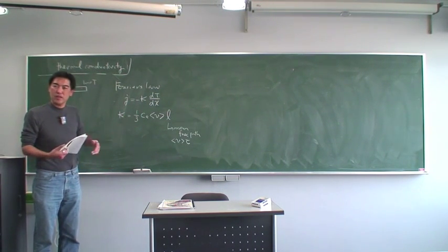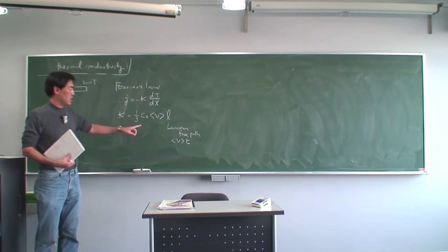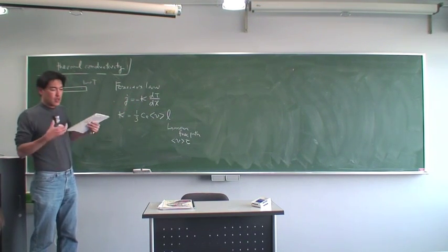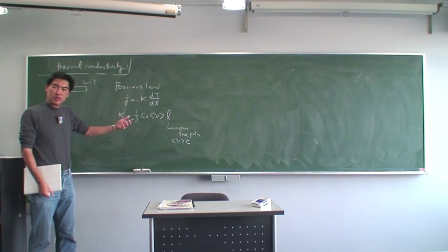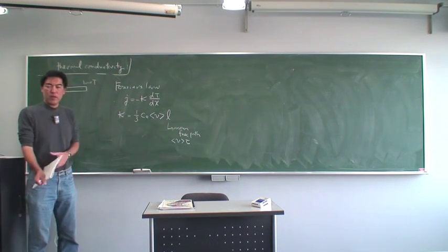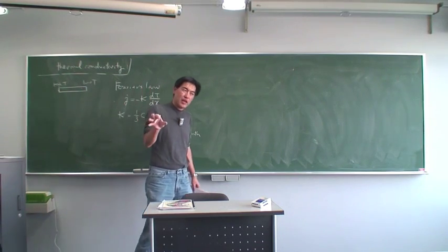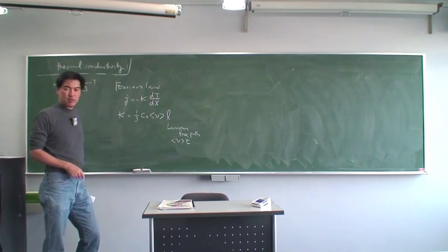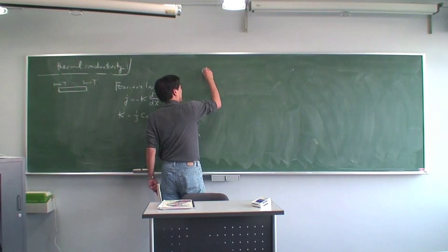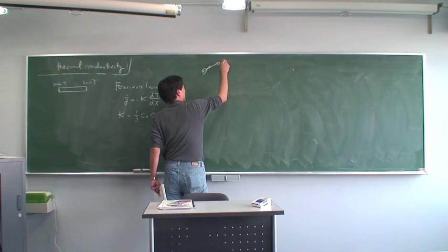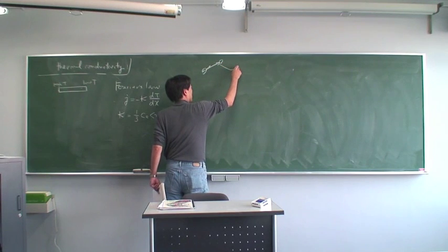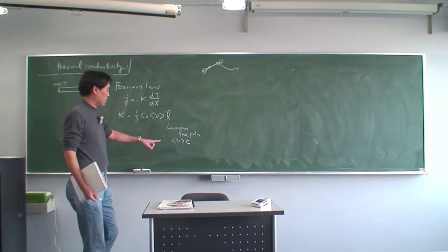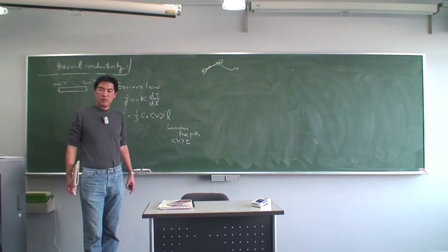Velocity: it is electrons that are moving, so the faster the electron moves, the faster the heat is transferred. After all, the electrons are carrying the heat energy. And L is the mean free path. Electrons move, hit something and stop, then move again and hit something and stop. That is given by velocity times relaxation time.